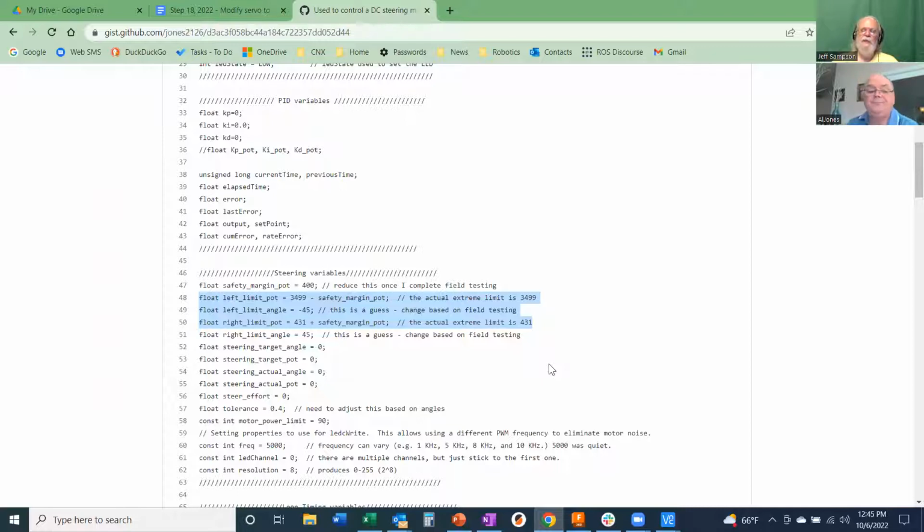Because if you're adding that tolerance in there, I assume it's because one or both of those potentiometers is noisy, and it could even be that your Ki, Kp, and Kd pots are noisy also. So you may have to average all of those pots to get a decent value, but that's something to consider.